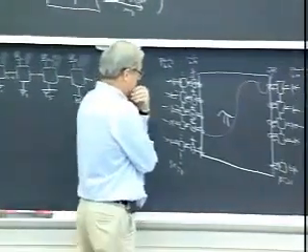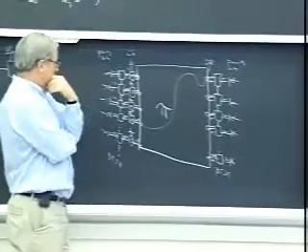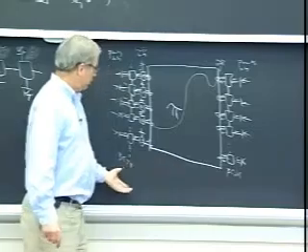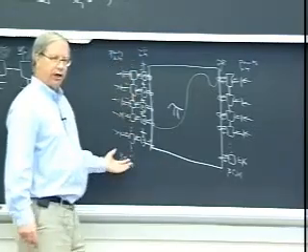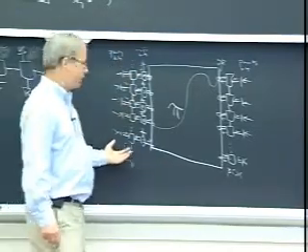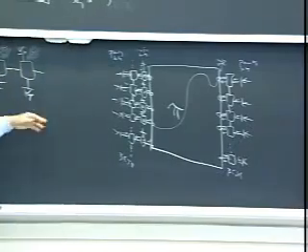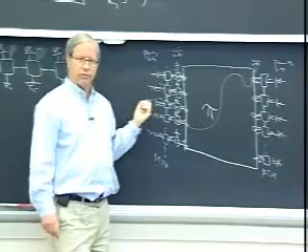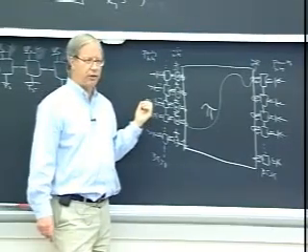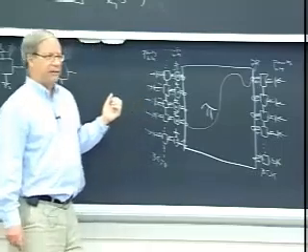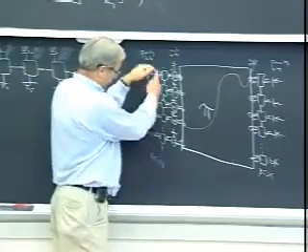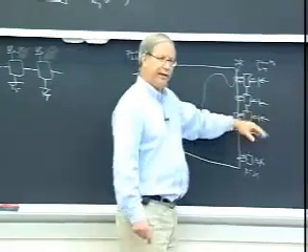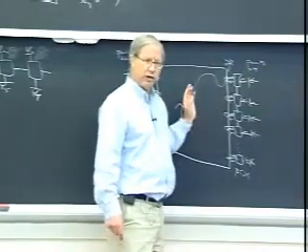Computation is not free. There's a marked difference in turbo decoding in that you're spending a lot more time decoding each side. This BCJR algorithm is a lot more complicated than just executing the sum product update rule for an equals or zero-sum node. That's a very simple operation. On the other hand, it doesn't get that much done. You can think of this as doing a lot of processing on this information over here before passing it back. Then this does a lot of processing before passing it back again.